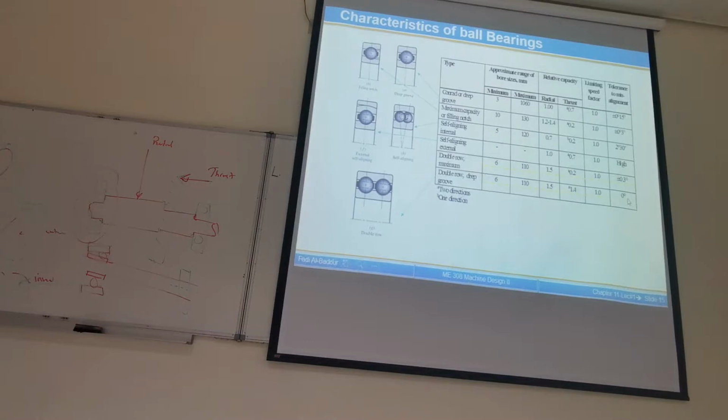It's becoming small, almost zero, as compared to the deep groove ball bearing. Now remember what we said about when you increase the width of the bearing, you are adding more constraints on the shaft, you're increasing the rigidity of the shaft. So it's becoming tougher to deflect or make a slope there.